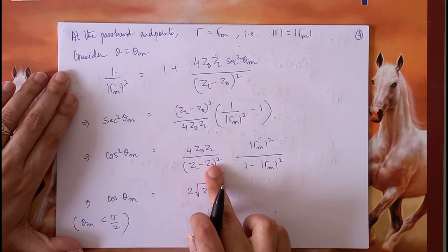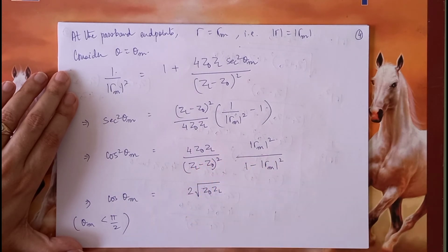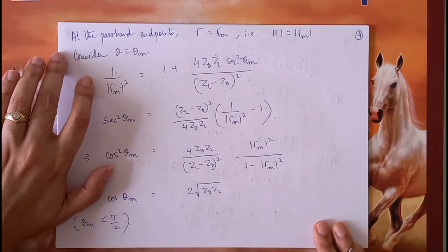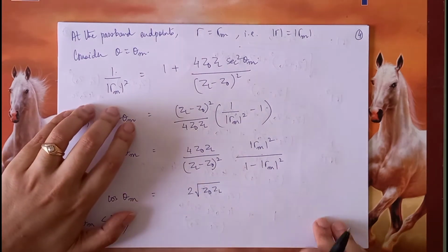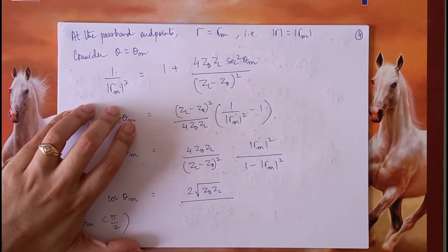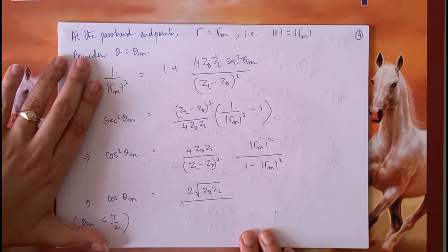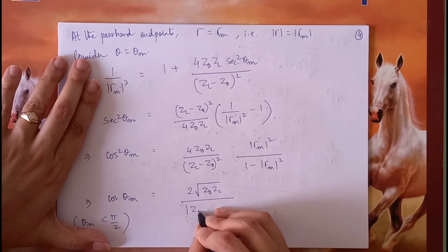Now zl minus z0 the whole square, the root will be when the square term will go, but zl can be anything, z0 can be anything. I mean, zl can be more than z0, zl can be less than z0, even though they both are real in this case. So therefore, to maintain the positive sign of the cos term, we will put a mod over here.